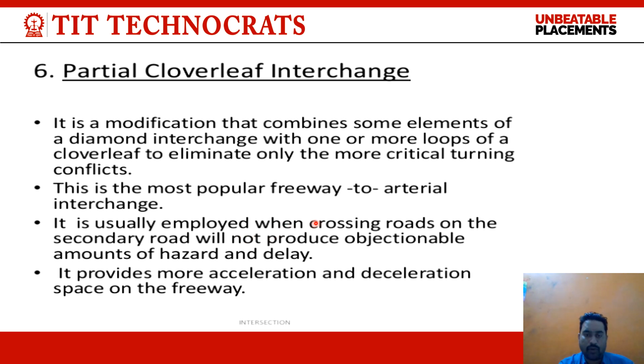It is usually employed when crossing roads on the secondary road will not produce objectionable amounts of hazard and delay. It provides more acceleration and deceleration space on the freeway.